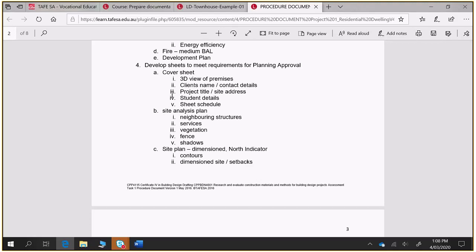Yes, exactly. What will probably be populated already for you within the drafting office is these general notes specific to various forms of construction, and you'll make choices as to, okay, with a steel frame dwelling, we're adding these notes, etc. But you might also want to be adding mention of your wind speed on there.